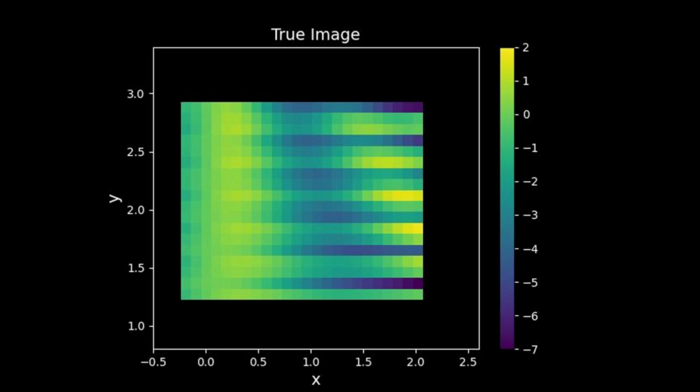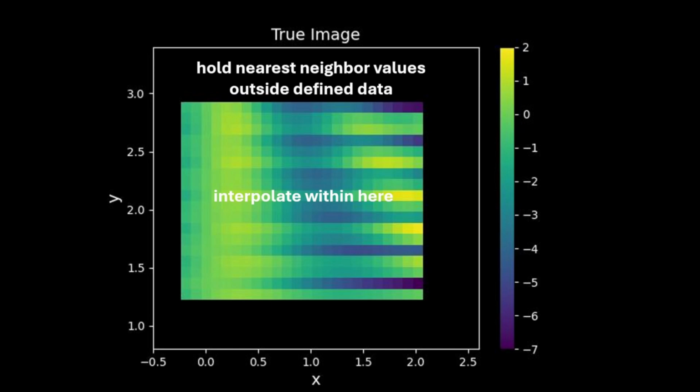So our interpolator objective is to interpolate accurately within the given data set and hold nearest neighbor values outside the data set. While going outside the coefficient tables in simulation should be avoided, a nearest neighbor approach is preferred to extrapolation. Because not only does extrapolation try to predict what we do not know, but extrapolation for the large number of coefficients in our buildup can produce erroneous results.